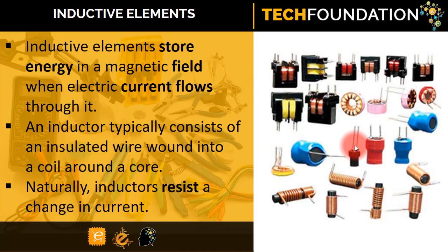Now, inductors play roles in power supplies a lot. If you look at the topologies for buck converters, those pulse width modulated or switch mode power supplies, we filter or smoothen the output voltage using inductors and capacitors in combination. So we shall look at them in details some other time.